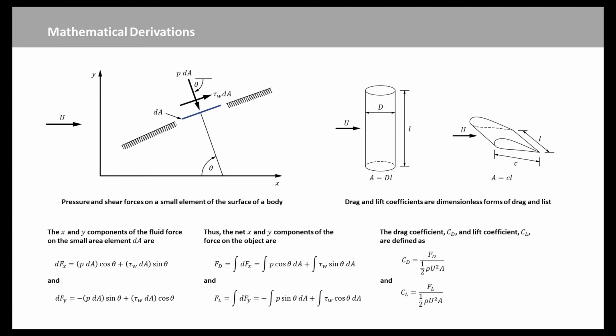The lift coefficient, C_L, and the drag coefficient, C_D, are defined as these equations, where A is a characteristic area of the object. Typically, A is taken to be the frontal area, the projected area seen by a person looking toward the object from a direction parallel to the upstream velocity, U, as indicated by this figure. It would be the area of the shadow of the object projected onto a screen, normal to the upstream velocity, as formed by a light shining along the upstream flow.